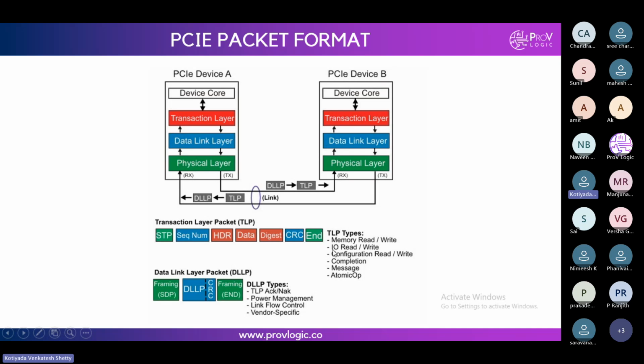In older PCI, we used the IO transfers. Presently no company will use the IO transfers. And coming to the config read and write, if you want to write or read to the configuration address, I will tell you why the config read and write are required. For suppose, every PCI device contains a 4 KB configuration space.